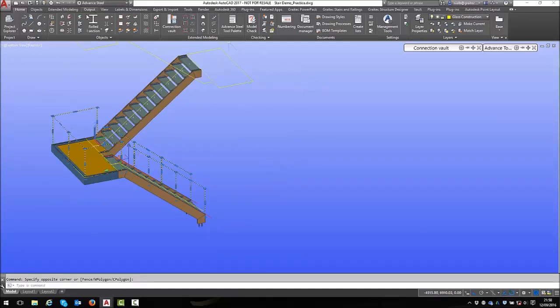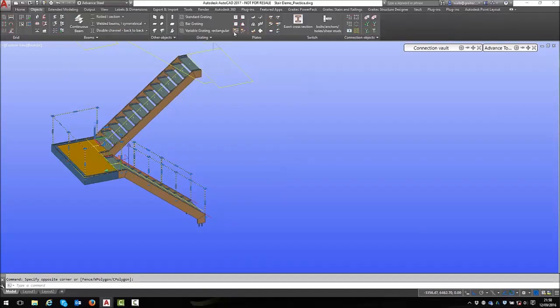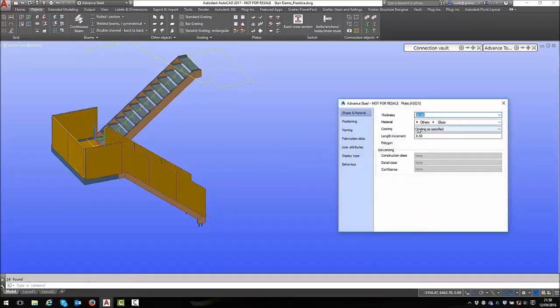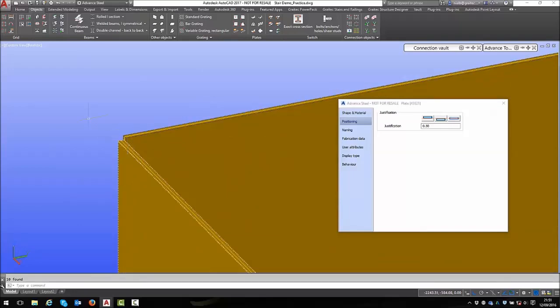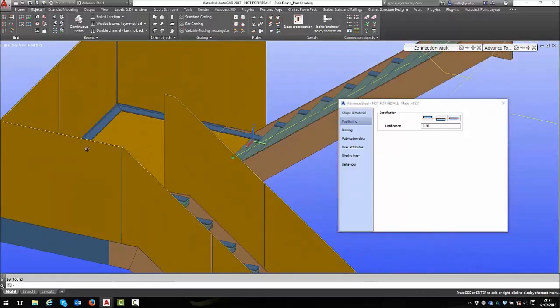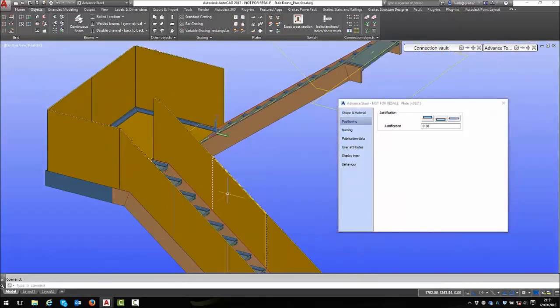Now if I select these, okay, that's it. All we're going to do, we're going to use beam at polyline. There it is. 50mm is going to be a bit serious, so we're going to make that 12mm. Glass, other, because it remembered it from the panel there. The position of it, I'm going to put it on the main line, center line of the glass panels. So there they are. Take you a couple of minutes to create these construction lines, but it's by far the most accurate way of doing that.